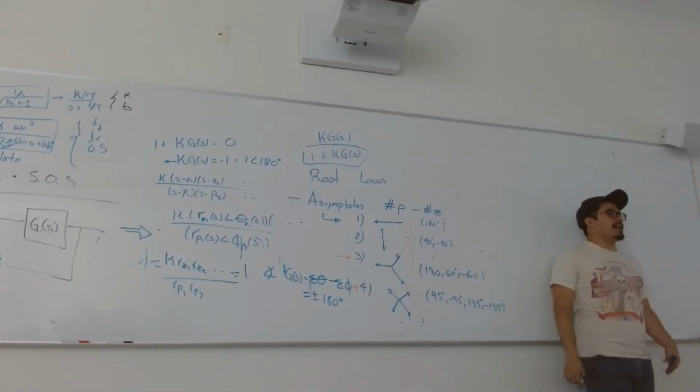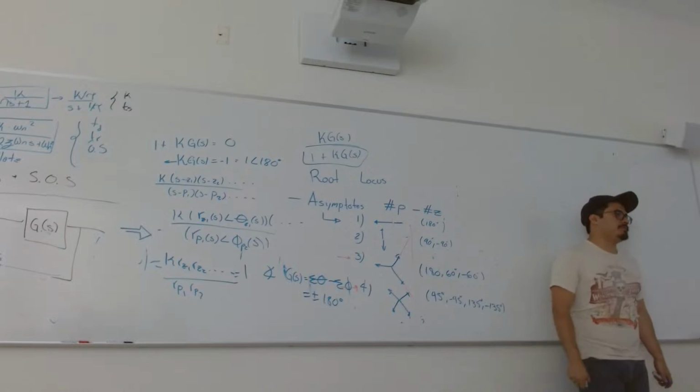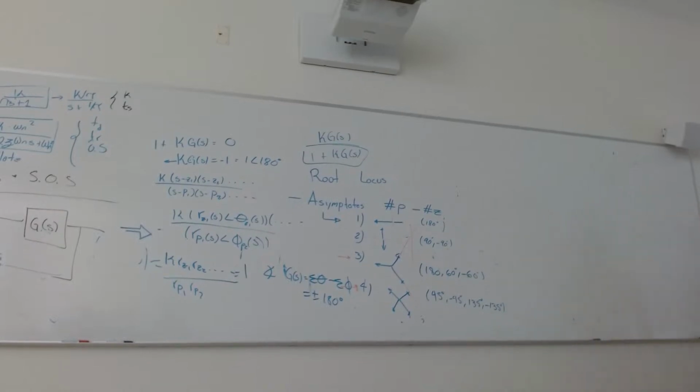What's the difference between an active filter and a passive filter? Active filters have the capacity of inputting energy into the system. If you use a filter with an op-amp, the op-amp has its own power source, therefore it can inject energy into the system if needed. Passive systems cannot. They only store energy and release energy, but they cannot generate energy.